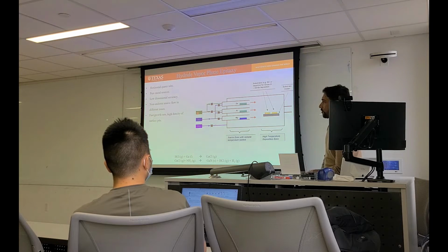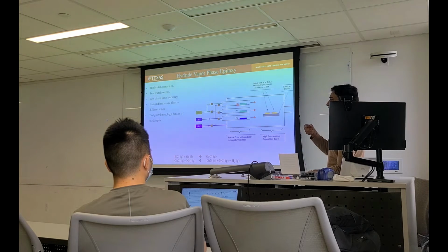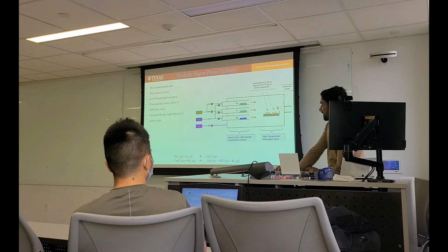So for growth of gallium nitride and gallium oxide, they use HCl gas. So HCl gas flows for gallium nitride. HCl gas passes through the gallium crucible. Okay, so gallium is in molten state. Its melting temperature is very low. So it just carries the gallium source from there, because HCl is acting as a carrier gas, and it just moves towards the quartz tube.